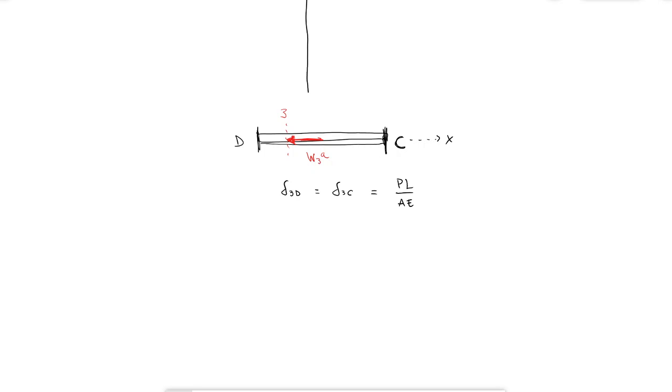The force that goes inside the section from 3 to D is going to be dx. We already had dy and dz to get the total d going towards the center of the gear, which is the radial force. Now we have this dx, which is in the x direction, the axial direction of the bearing.